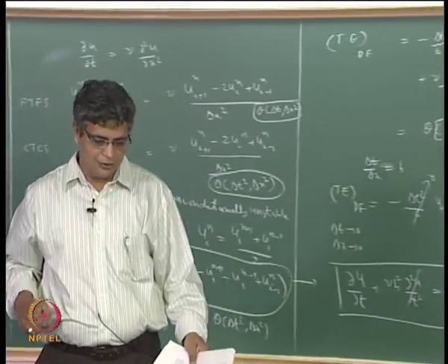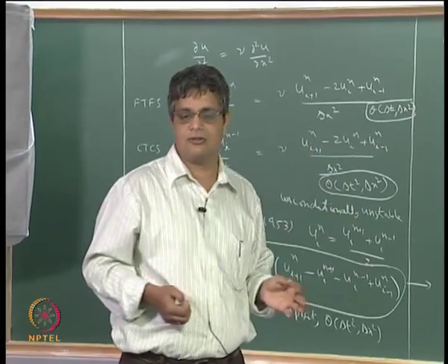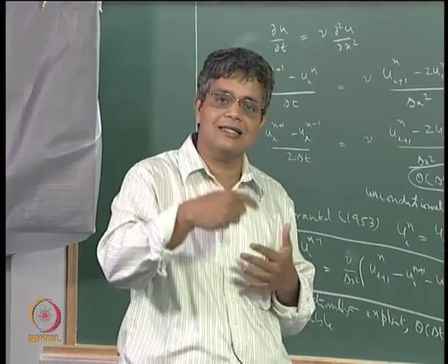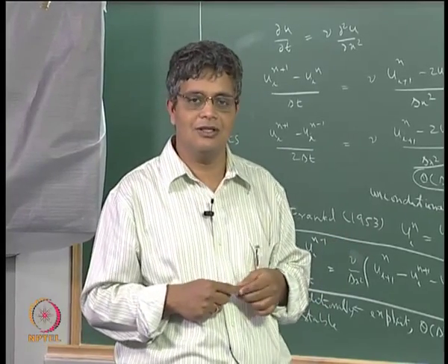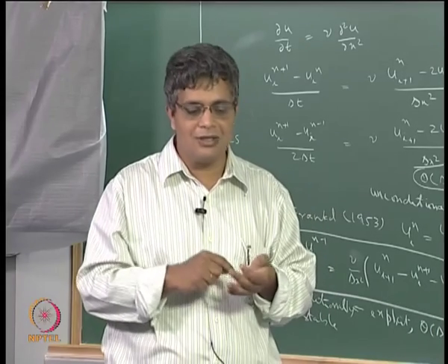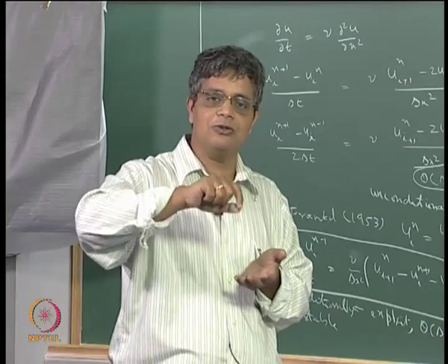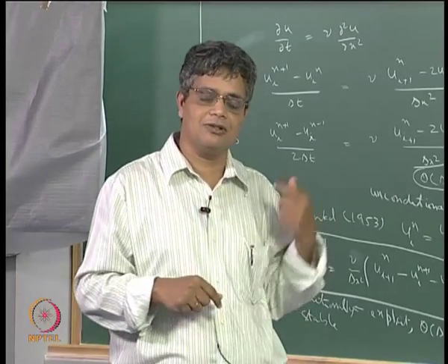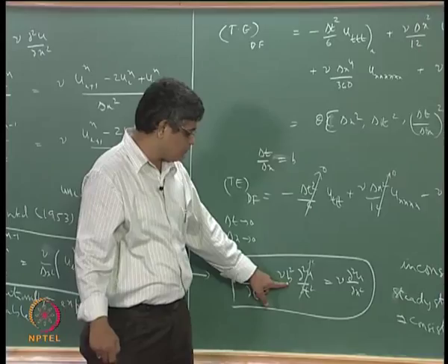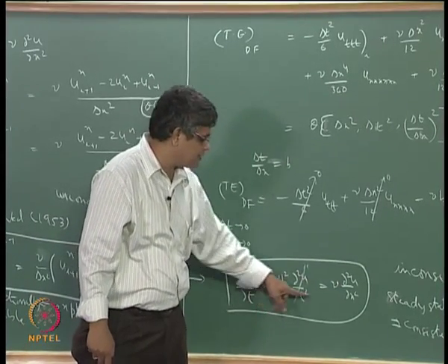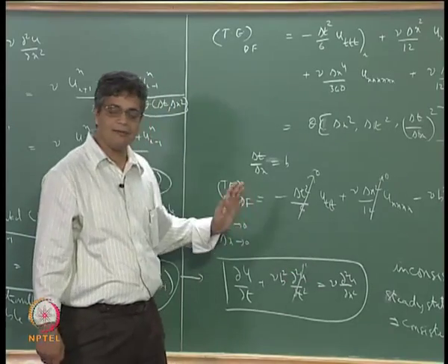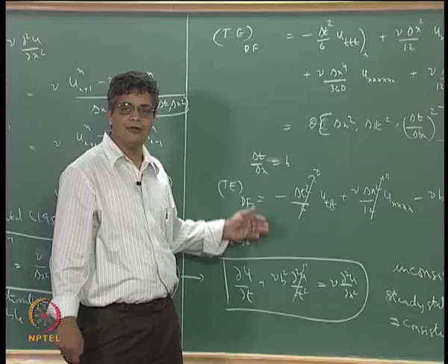Okay, so in that sense if you are looking at a steady state solution from this transient solution, which is very commonly done in CFD solutions, because that is probably one of the ways of overcoming the inherent nonlinearity contained in the Navier-Stokes equations. So in such a case the final solution is not arising from an inconsistent discretization, but the way to that steady state solution is definitely going through an inconsistent approximation of the governing equation. So whatever error that arises from this term, which depends on what the value of b is and what the value of the second derivative is with respect to these other terms. So depending on the magnitude of this as opposed to the magnitude of these two at a particular time and space will actually determine the accuracy of the time dependent solution.